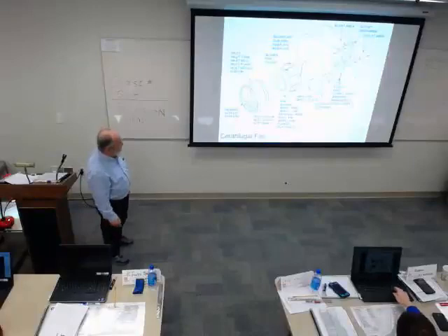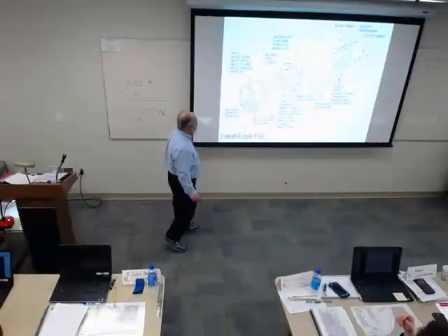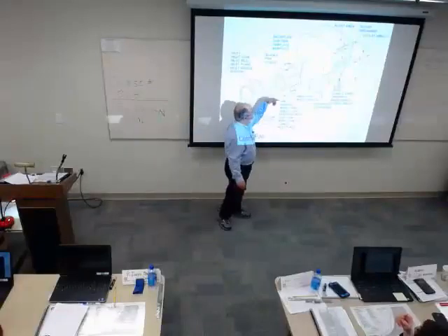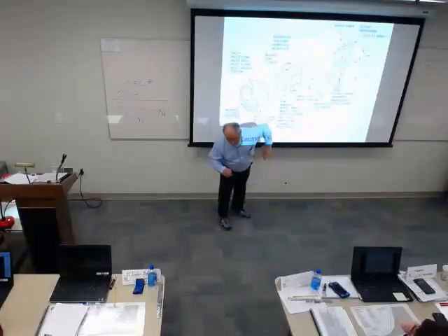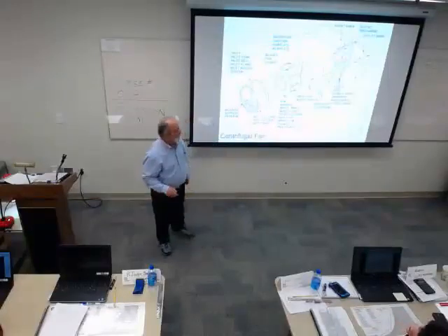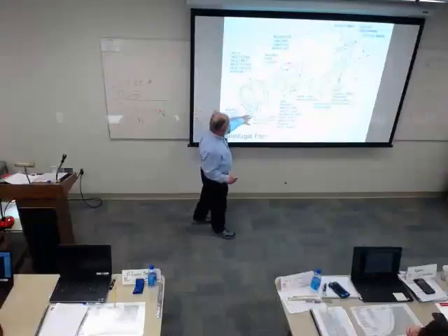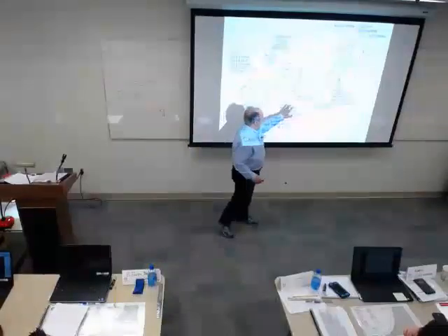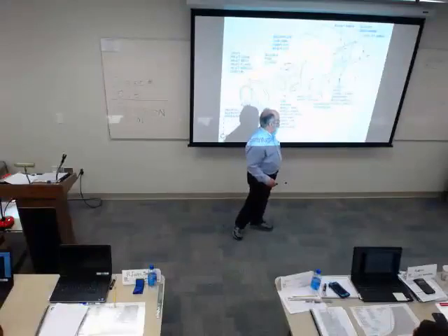Here's a typical centrifugal fan. It's a backward incline. The thing rotates this way, and you can see the blades are slanted so that it rotates like that. That's the backward incline. And here are some typical parts. We've got the inlet collar. This is called the impeller, what we'd call a wheel or sometimes rotor.